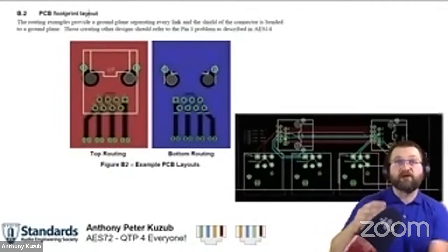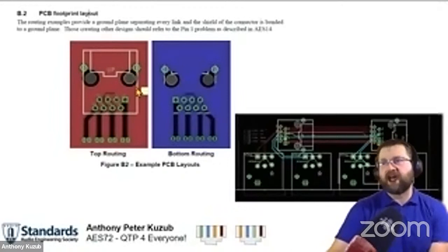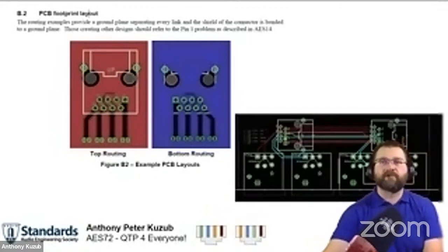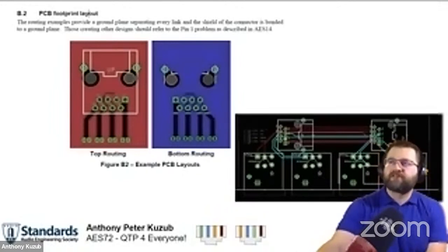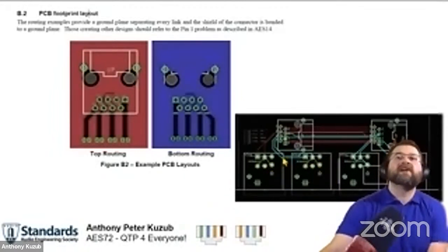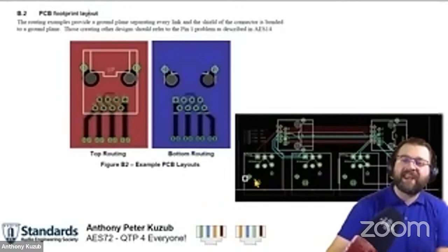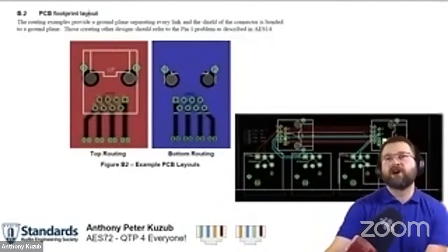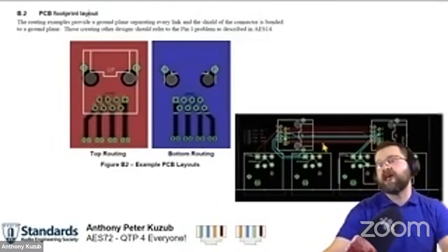It goes on to talk about a footprint layout. I regret doing this, and I think there's a problem. We'll revise this because, like I said, it needs to have that shielding consideration. But by breaking out those pairs, you can simply do 1, 2, 3, 4, and away it goes. A lot of those boards and circuits I was showing above have a footprint. It's an A footprint. Neutrik and Amphenol make a footprint where the A male and female can actually stack on top of one another. So if you were to make one of these little PCBs, you can put that A style footprint on it, have the male and female on the same footprint, and break it out into RJ45s. But in this case, I don't really have a chassis. I really don't have anything to deal with.